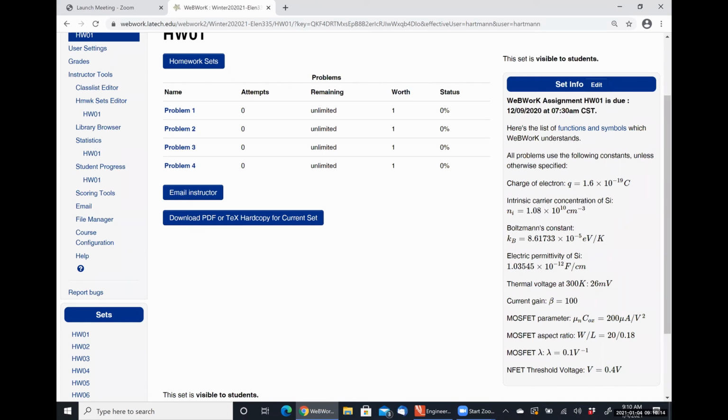I'm not going to make you do any load line analysis where you have to accurately plot an exponential curve and then find where that point intersects with the load line to determine the operating point of the diode, because that is painful. It would be wildly difficult to make you do that in a short amount of time. A lot of the problems from the book require that method. But by using your calculator, if you can get the equation of the load line and the exponential model and set them equal, your calculator can solve it without all that plotting.